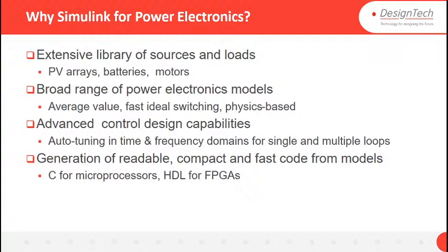Model in the loop means the model which you design in Simulink and test. Further, you generate embedded code or FPGA code, STL code, and test that code. Then processor in the loop means you deploy your controller on the processor or controller hardware, and you test the controller.